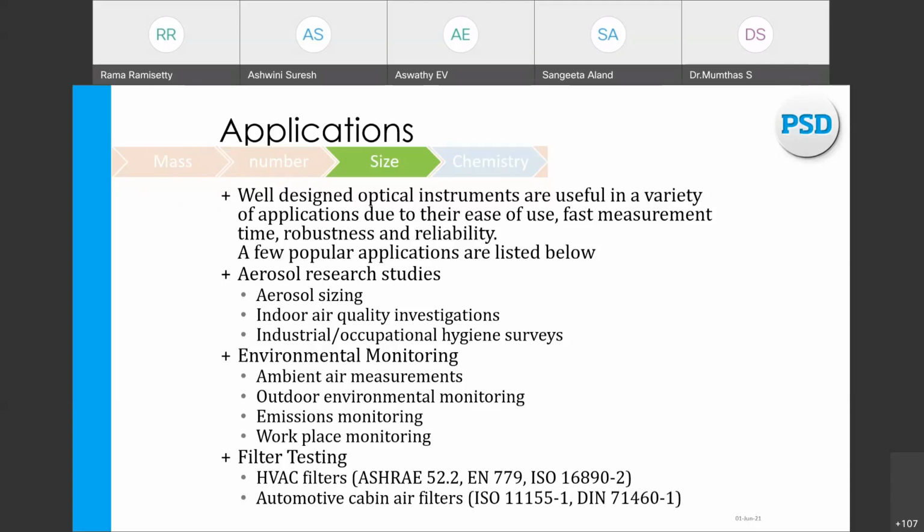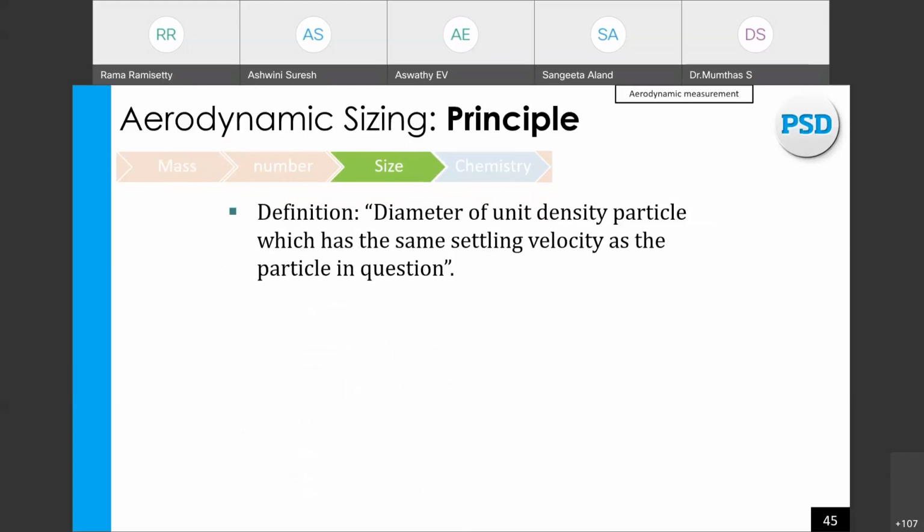In general, the light scattering method is the cheapest method, and you can measure particle mass, size, and number at a time. Another gold standard equipment is for the larger particles. So far we have seen nanoparticles, where we have the scanning electrical mobility method, and for bigger particles, we have optical methods. If you want to measure even bigger particles, for example, up to 20 microns, with more accuracy and with more channels, you have to go for